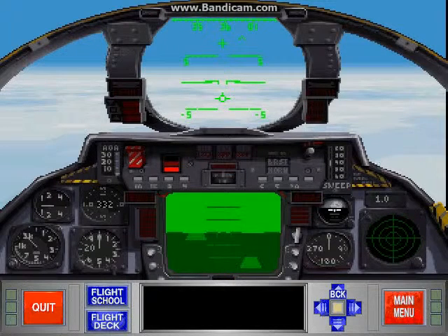The F-14 is designed with movable wings that automatically take advantage of various flight conditions. The position of the wings is called the wing sweep and is displayed by the wing sweep indicator. As you accelerate, the wings automatically sweep back, so you are configured for high-speed linear flight. When you need more lift and maneuverability for tight turns, dogfights, and landings, the wings sweep forward as you slow down. By looking at an F-14's wing configuration, you can gauge the relative speed of the aircraft.